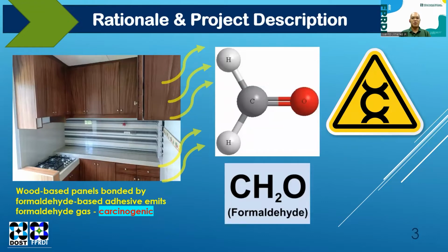Any wood-based panels bonded by formaldehyde-based adhesives can emit formaldehyde gas due to the presence of free formaldehyde, which can escape from the panels. This formaldehyde gas, based on studies of the World Health Organization, is carcinogenic and may possibly accumulate in the body through prolonged inhalation or exposure to it. Hence, formaldehyde emission from wood-based panels is regulated by various countries such as USA, Europe, Japan, Australia, and New Zealand. In the Philippines, formaldehyde emission recently became a mandatory test that needs to be passed by plywood manufacturers.